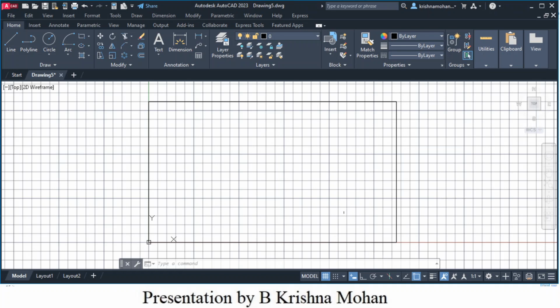Now I will create a title block. To create a title block, I will use the lines that represent this rectangle. Since we created a rectangle, all the lines are active when I select it. What I'm going to do is explode this rectangle so you can have individual lines as individual entities. You can observe the change. So let me use the explode option.